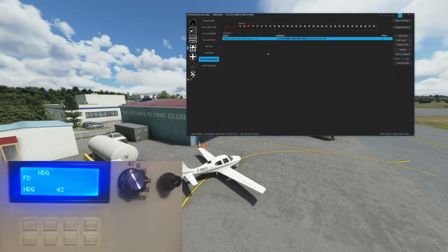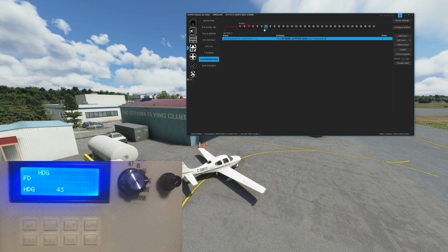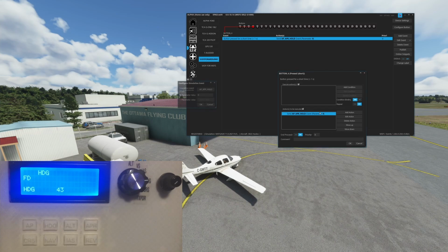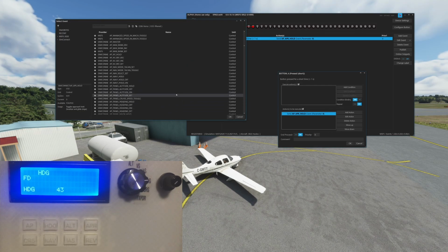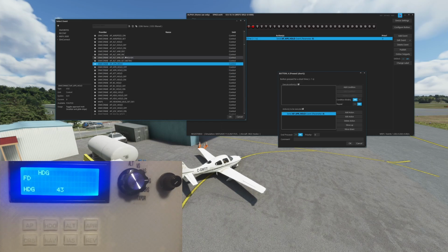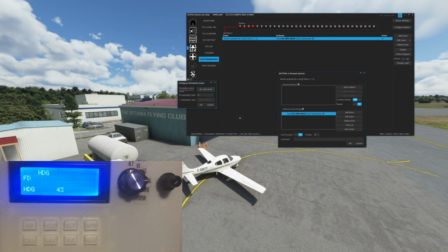Then we came over to the next button, which was our altitude. Same thing. Panel altitude hold. That way it enables the button, but doesn't change the preselect and go to an altitude capture of where you're at. Approach mode. So we've enabled the autopilot approach mode hold. So because there was no panel approach button, we had to use the mode button. But again, this doesn't change other values. So it behaves in a similar manner and toggles approach mode on and off.